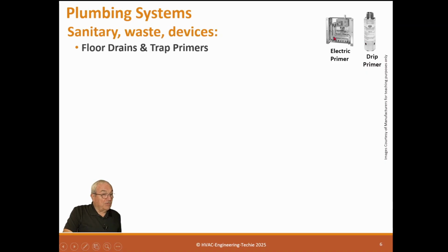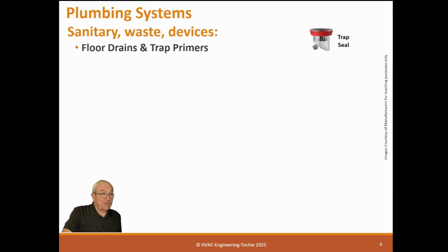This is an electric one, and this one you put in the wall, and this might go to 4 or 5 different traps, and it just basically turns on every few minutes, maybe every day, and puts in enough water to fill the trap. And that's so you don't forget. Because if you have just a regular trap, the water will evaporate out of the trap, and then you won't forget because it will put gas into the system, into the space.